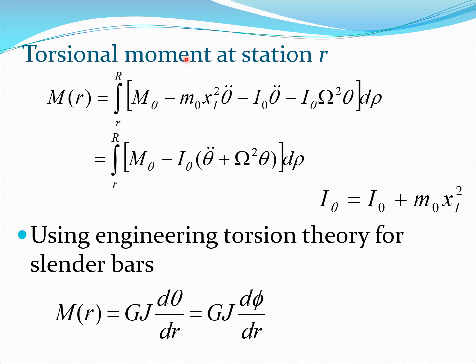Now, if we observe this very closely, we will again see that the three negative moment components are the restoring components, and the one which acts to increase the moment is m theta. So now we use a certain fact from geometry or basic mechanics, that is I theta is I0 plus m xi square. So this is by simply moving the moment by this distance here, I can write this equation, and therefore I can write the term I0 plus m xi square as I theta.